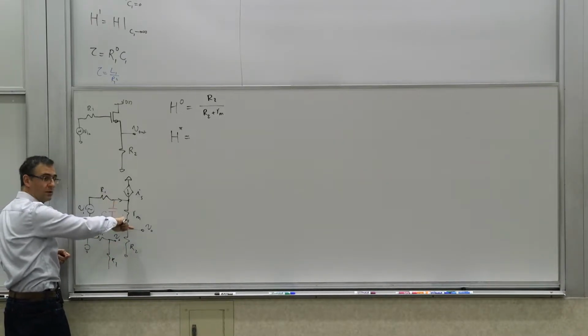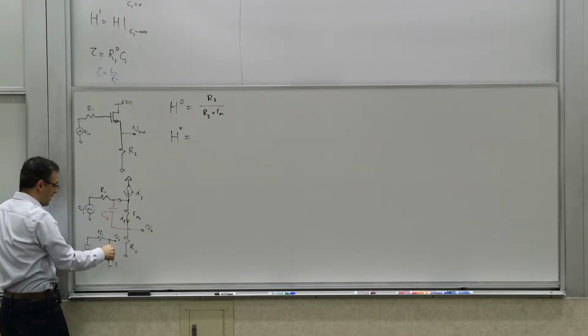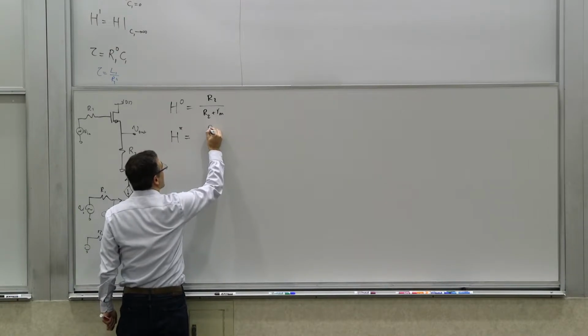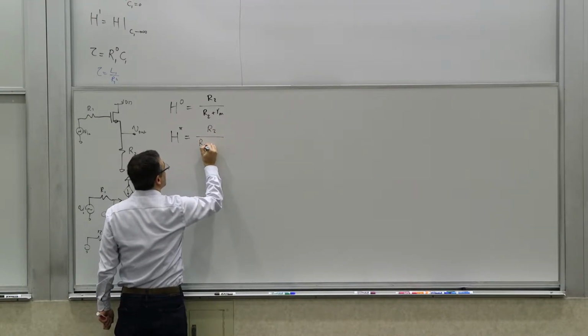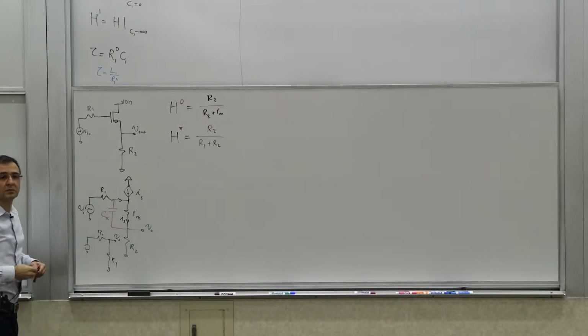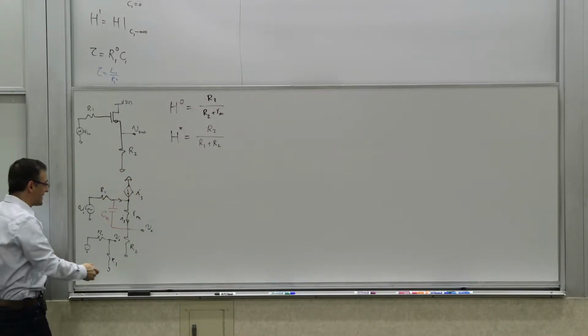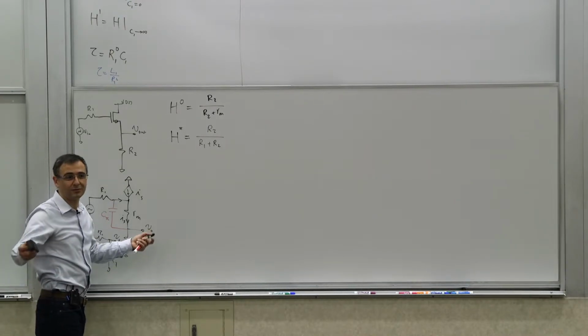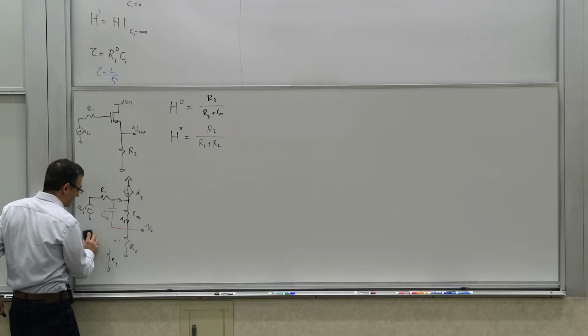If this is shorted, right? So this is the resistive divider. So what is the gain of this thing? It's R2 over R1 plus R2. Right? Now, you can see these calculations are actually pretty straightforward, because you're short circuiting stuff, so you're taking stuff out.